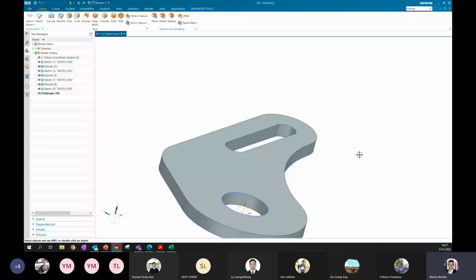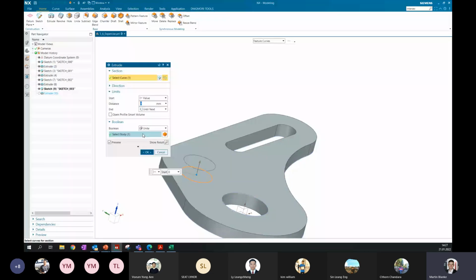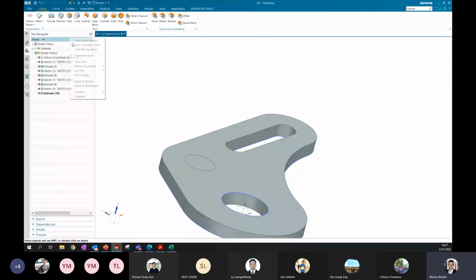So you are responsible for the manufacturing files, and if you want to export, for example, a step file or something like this, you have to select your bodies. So maybe let's take a look at this point because it's a very important point. At the moment, I have only one body, and let's change this option from united to none. I have two bodies, one body, the second body.